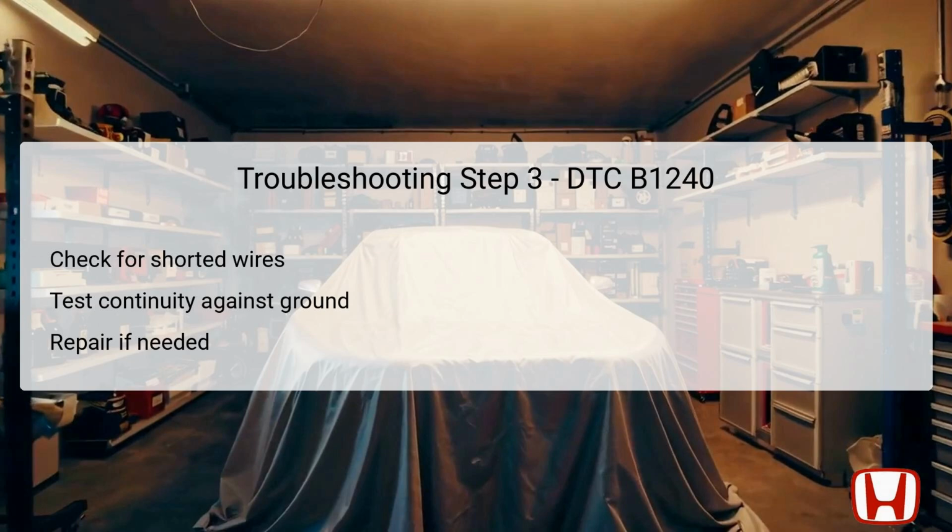For the mode MTR-DEF circuit, check continuity from the climate control unit 32P connector number 5, GRN, to body ground. And similarly for the mode MTR vent circuit from the climate control unit number 6, WHT, to body ground. If continuity is found, it confirms a short circuit situation, requiring appropriate repairs to rectify the short to ground. Conversely, if continuity is absent, this indicates the mode MTR-DEF and mode MTR vent wires are intact, allowing transition to